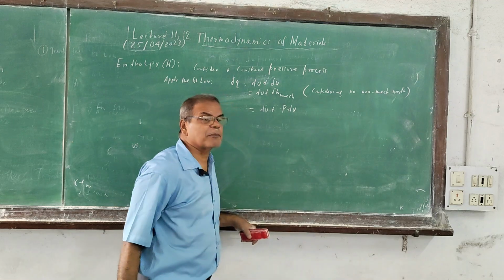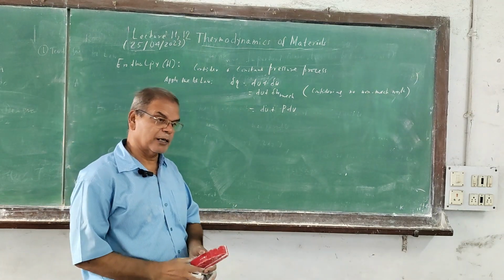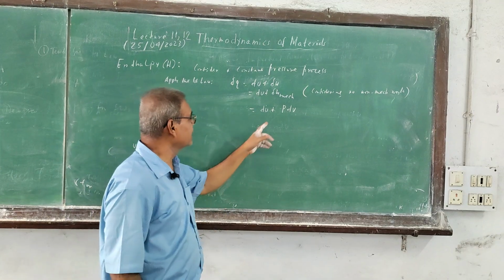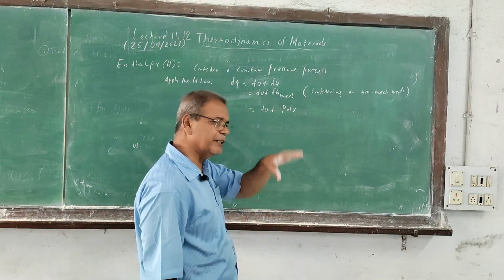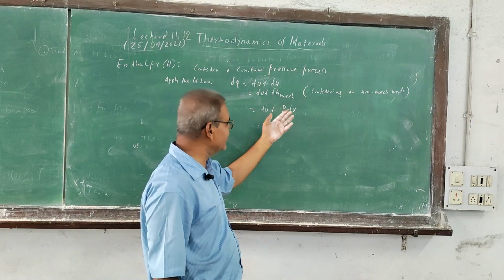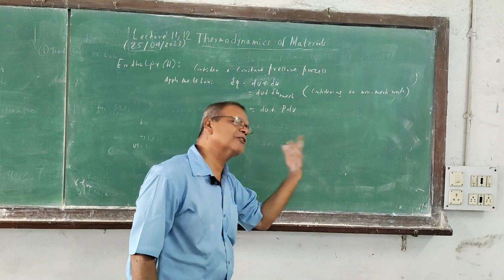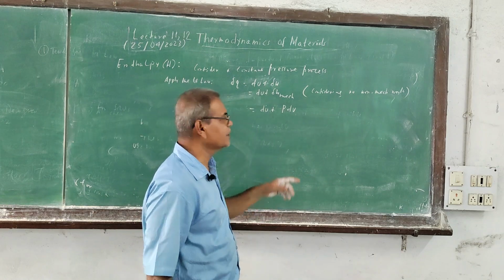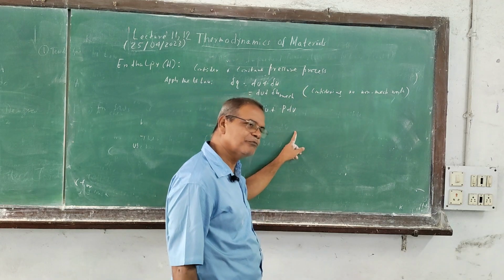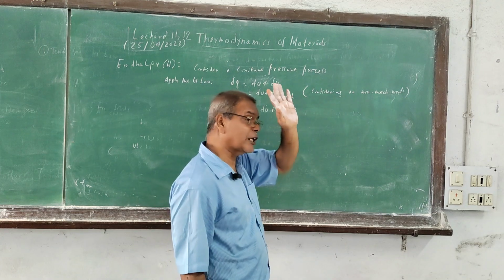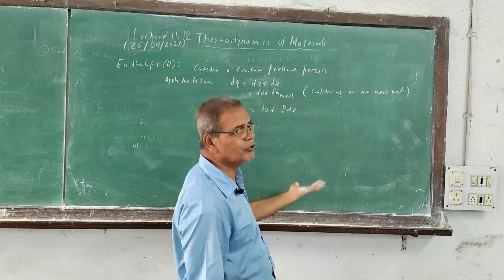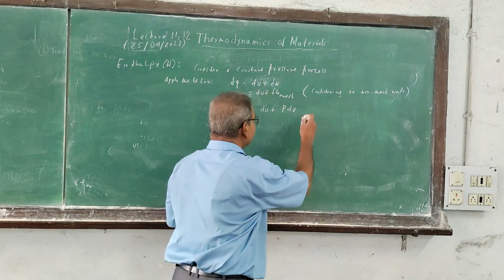It is a constant pressure process. Remember, I gave you an outline there. It is actually the same work. Reversible, irreversible, same in constant pressure. So that's why PdV both. If it is reversible, PdV; the irreversible also PdV. Means all PdV, since constant pressure. So for constant pressure and constant volume, PdV. Not for isothermal and adiabatic. And constant volume, then it is zero. Both zero. So okay, note this.